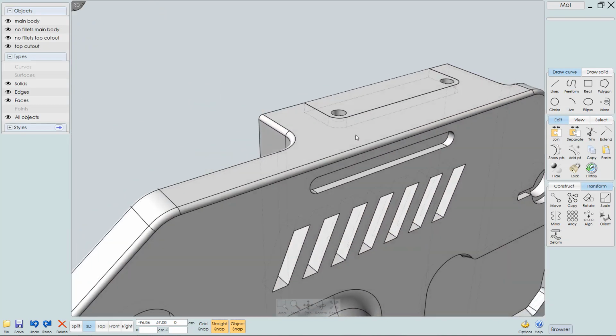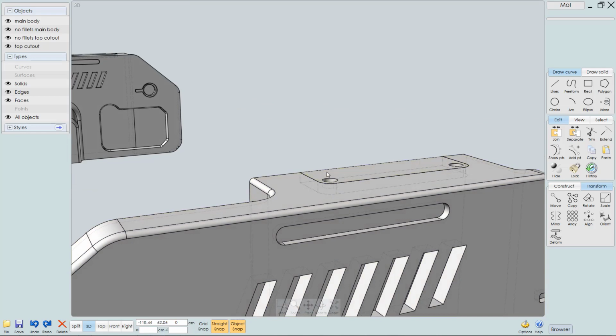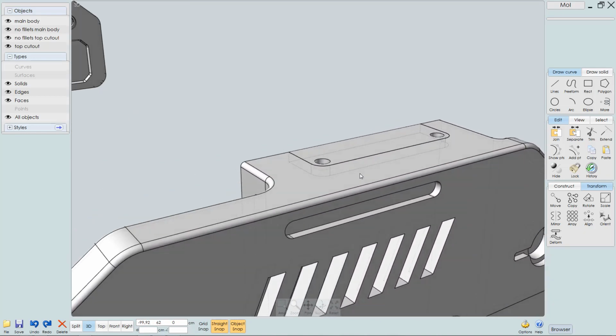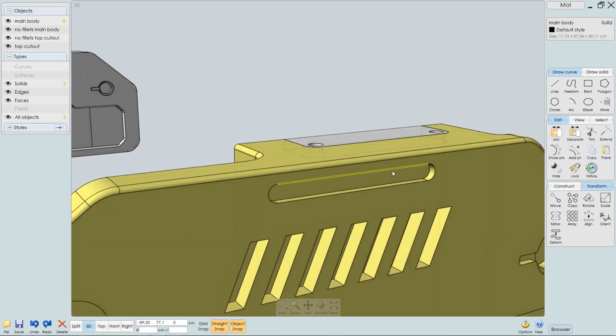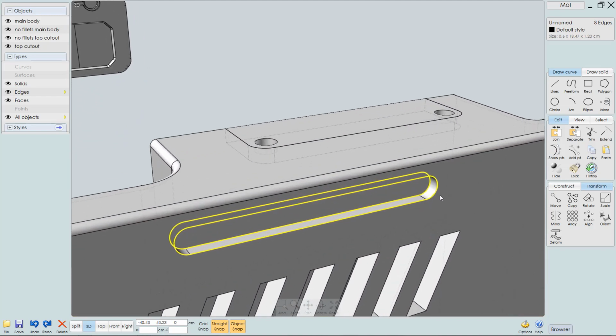and let's continue. And this is taking a bit because we just can't fillet everything with the same settings. It would just not look good. So let's continue with these edges here. And here I should actually be able to do a loop selection. My shortcut for that is Shift L.